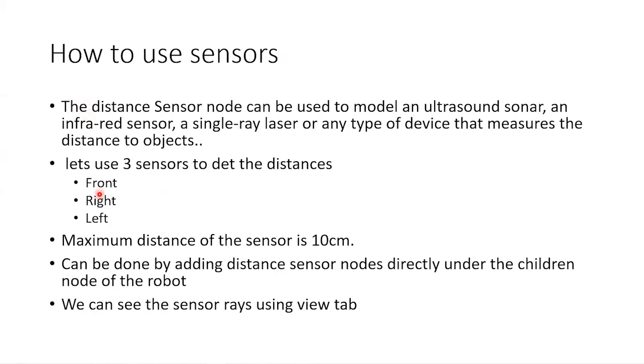In here we are going to use IR sensors to get values from the environment, to get the distance from the obstacles in the environment. And in Webots, usually the sonar type devices are the devices that measure the distance using any type of ultrasonic or IR or rays. As examples, IR sensors, ultrasonic sensors, and even laser sensors are under this category.